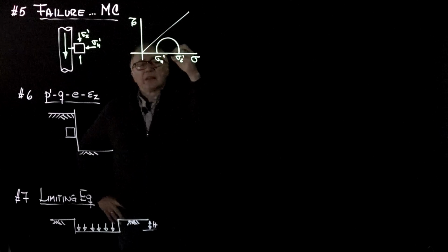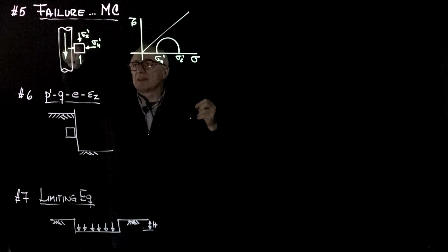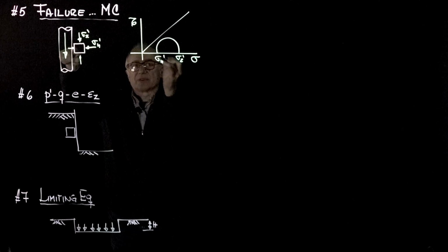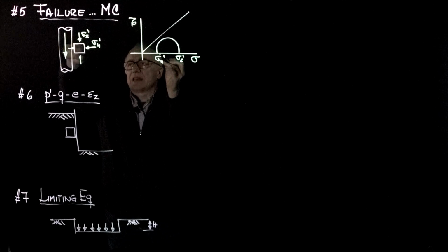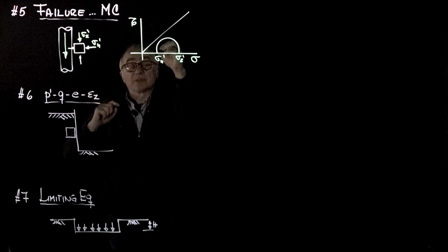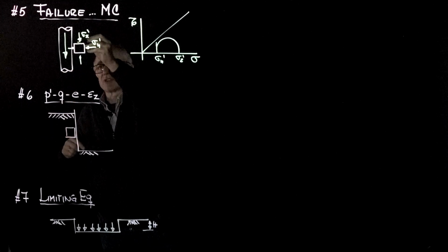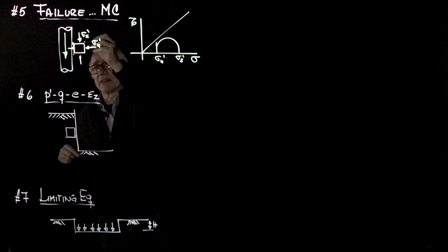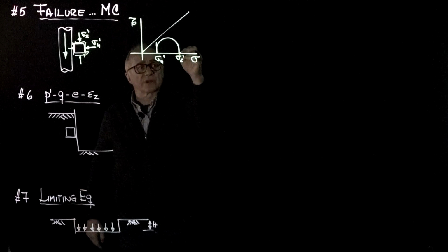So by the time we add shear, let's say that on the face here that plots horizontally, let's say that we take that one as our face, we're going to plot shear downwards because it creates counterclockwise rotation. We're going to say that it's positive. So shear will appear here, and at the same time, because of reciprocity of shear stresses, shear will also appear on the other planes. And so this will be the state of shear. This element will actually go down.